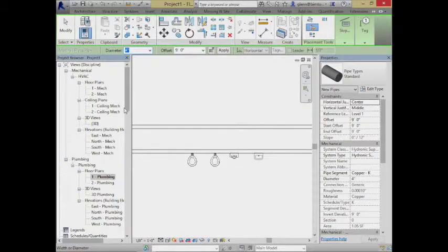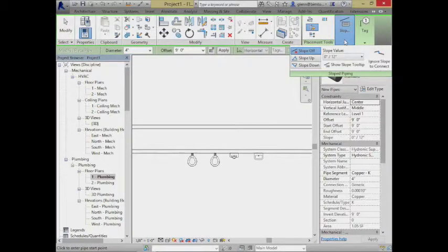As we think about this pipe and what its offset is, I tend to use a very small offset. If this has to be around 18 or 19 inches, I'll let this be like 6 inches or something like that. I definitely want it to go down. But we have the issue that, as we put the pipe in here, this pipe's going to have a little bit of slope too. So let me show you what the slope choices look like.